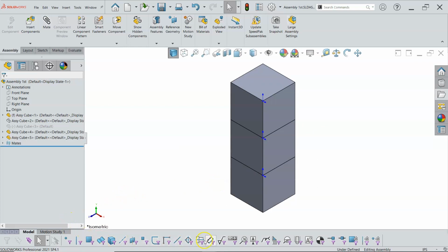When we do F5, I have the filters across the bottom. If I'm having trouble making selections in the assembly to perform the mates, I can default to filter faces by hitting the X on the keyboard or clicking on the icon. Surface bodies, solid bodies, axes, planes, sketch points, sketches, segments, midpoints, center marks. Some of these are going to be for the drawing. And then the vertices.